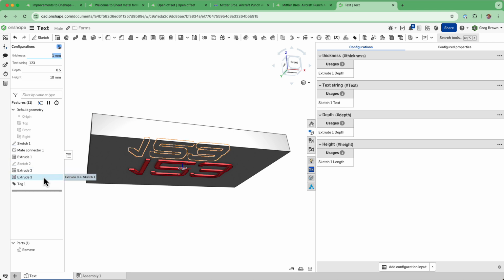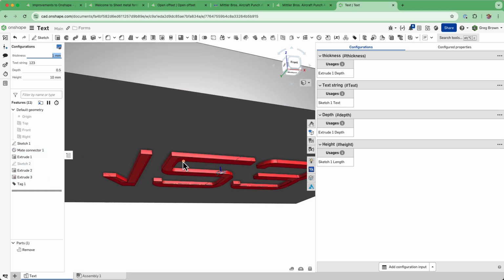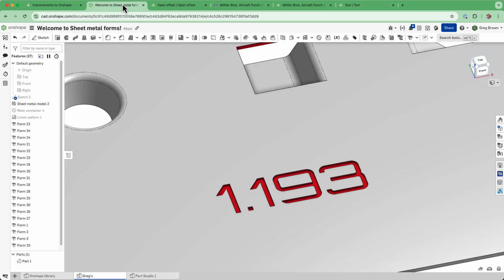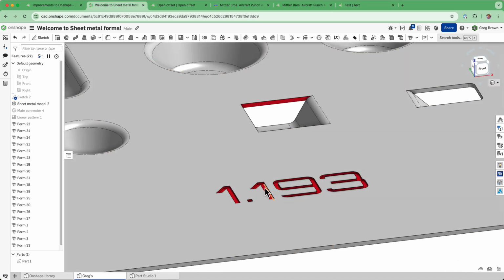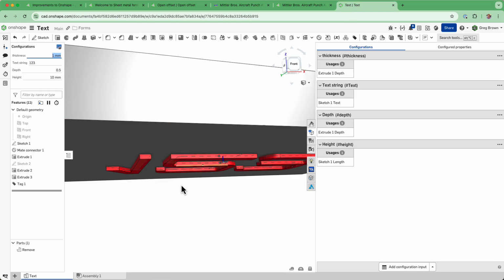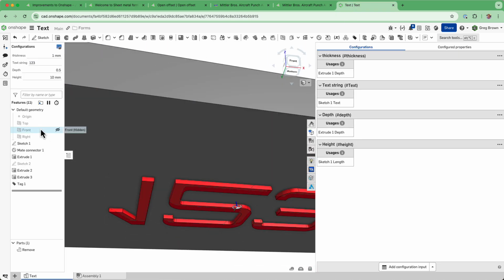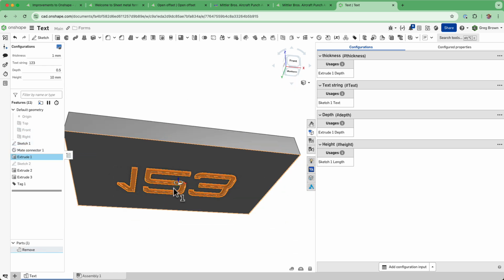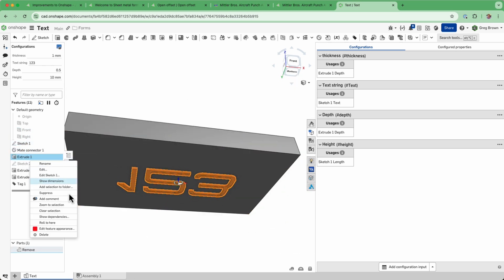I have used a trick to color all of the faces, again, so that when we look at its use, it's going to be coloring the faces on the other side as well. That's just a really interesting side effect. And the way that you color these is you look at the feature that created that extrusion, right-click, and say there's a feature appearance.